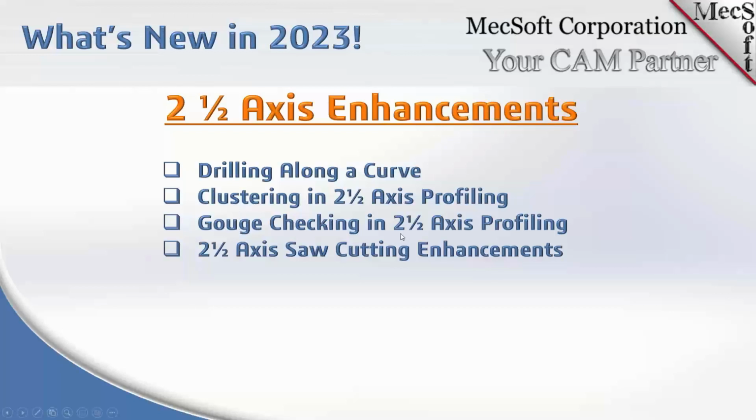This command will actually throw down a 2.5-axis profiling operation based on the outer perimeter of all of your curves. It won't gouge any of the other curves that you have selected. It'll just go around the perimeter. So that's pretty exciting. I think that's going to save you a lot of time in debugging your curve geometry in order to create a closed perimeter curve.